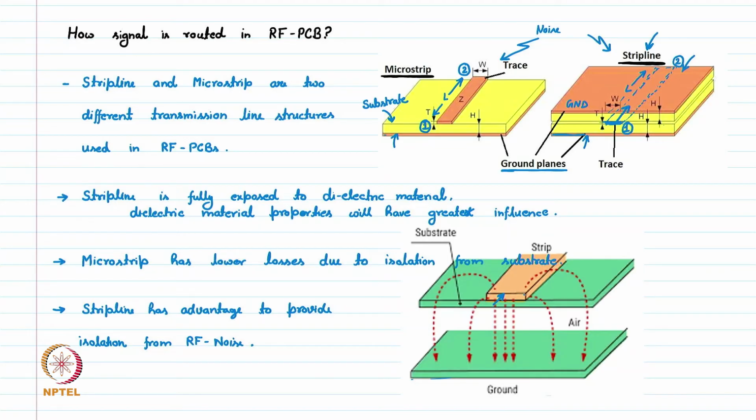this microstrip is coupled to the ground plane through this path. All these electric field lines will be starting from microstrip and going all the way to the ground for termination, in all the directions. So, this is how the microstrip is actually coupled to the ground plane. Now, let us discuss microstrip as a transmission line, how it works.